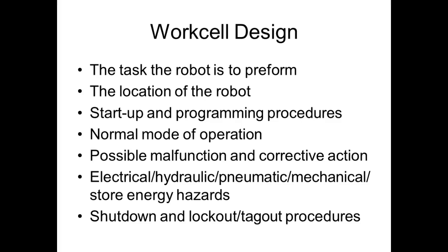Lockout, tagout. And you're supposed to lock out and tag out not only the electrical energy, you're supposed to lock out and tag out every power source. Everybody understand that? If you've got power sources that store energy, then you need to do what? Leave that energy off. That gets a lot of people hurt too.